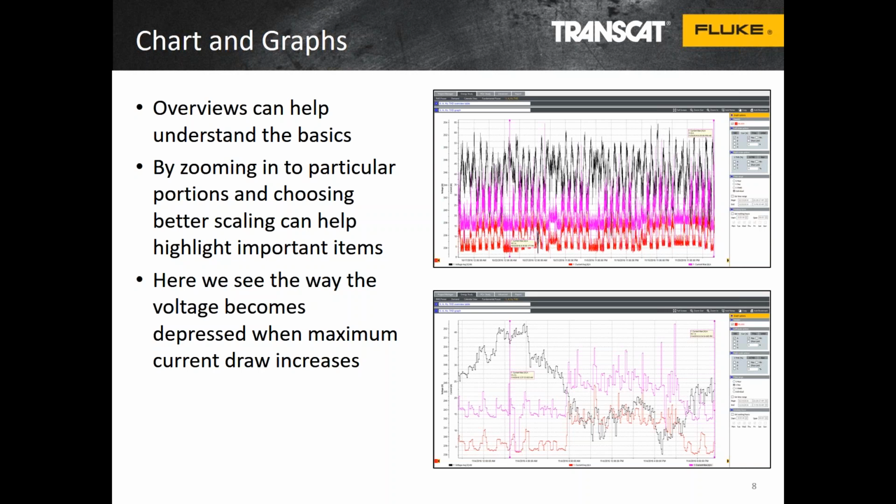What we don't want to see is the voltage going down really significantly below the level that we'd expect when loads switch on. That could be an indication that we're overloading the circuit, or that the facility is overloaded, where we're drawing too much current and the source of the voltage doesn't have enough capability to supply. Because at that point, then you may be getting voltage dips, you may be getting sags on the voltage, which would cause problems for equipment. Maybe they'll just reset accidentally, or maybe breakers will trip because of that. So these pictures at this level are really important to best understand.